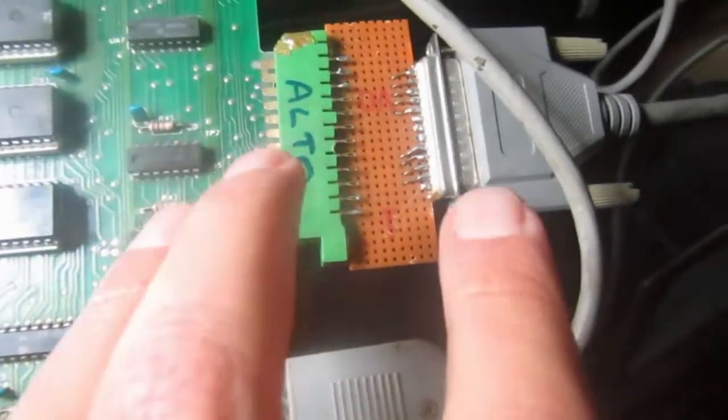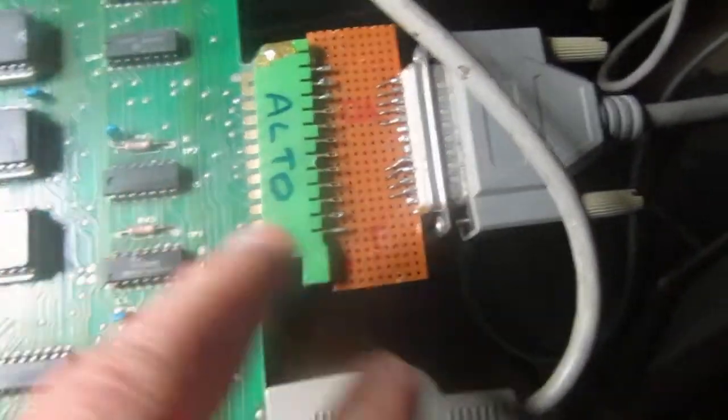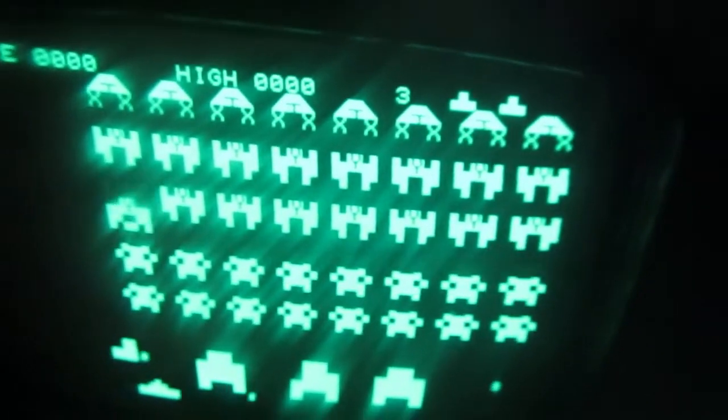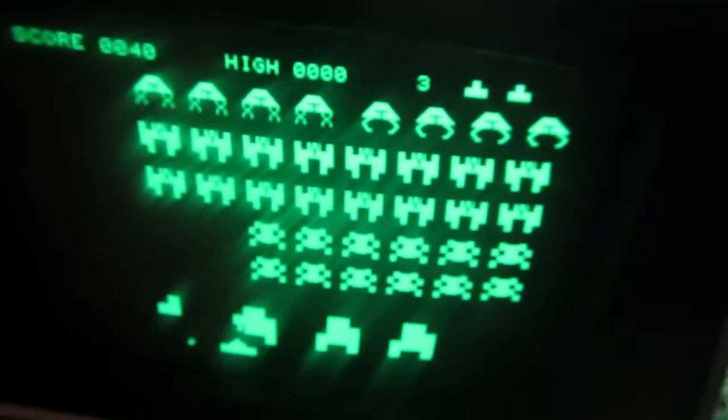So as you have seen on the sped up video, I've checked both the tape ports, the IEEE interface to my disk drive, and this one first didn't work, so I tried just cleaning the contacts, and that solved the problem. And the last thing I usually test is the user port, connecting my laptop with CBM link and sending some programs. I like to use Space Invaders as a final test on PETs, and so everything works fine.